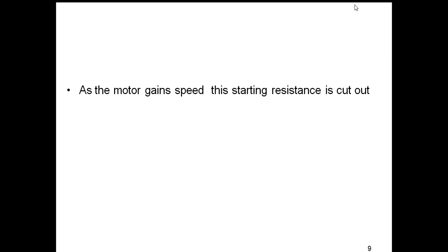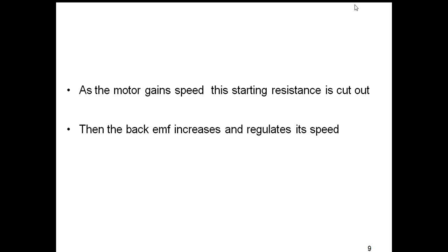And when the motor gains the speed, this resistance, that is the starting resistance, is cut out, because then the back EMF will increase, and this regulates the speed of the DC motor.